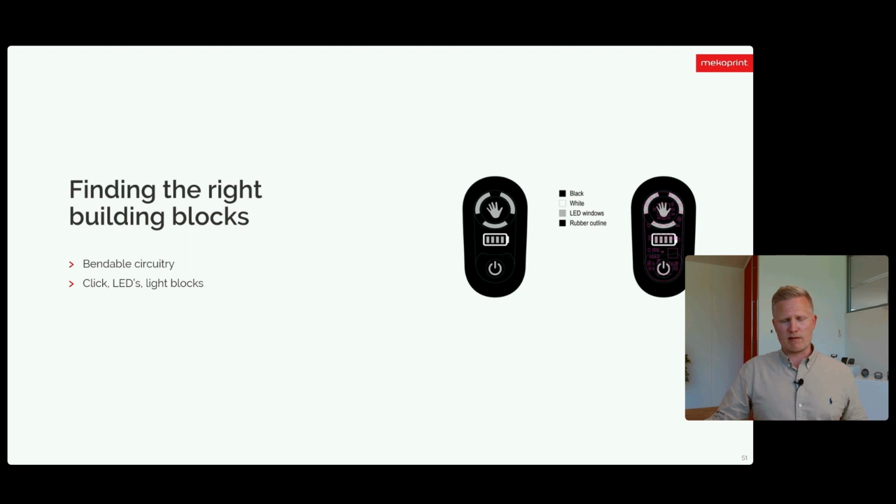As mentioned, very limited space, a very small keypad. We also had to figure out how we can do a good click on such a small space. And as mentioned earlier, when you have limited space, we might not use metal domes. So we had to use tactile switches because a tactile switch gives a better click than a small metal dome. We also had to place the LEDs and the light blocks optimally to maximize the illumination.